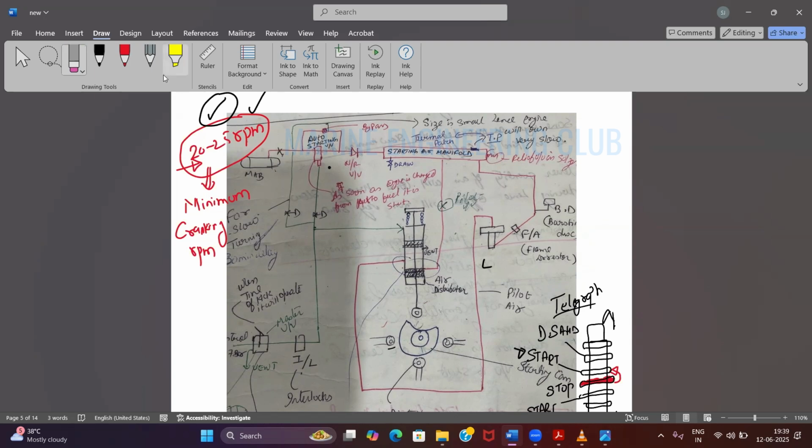Okay. So you have vent, interlocks, and the master valve also you can say. Then the slow turning valve. The auto starting valve is also a kind of safety. As soon as you're cranking RPM, that slow turning valve, the 7 bar is given, it will shut off.